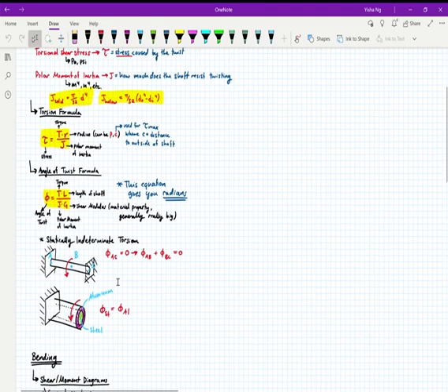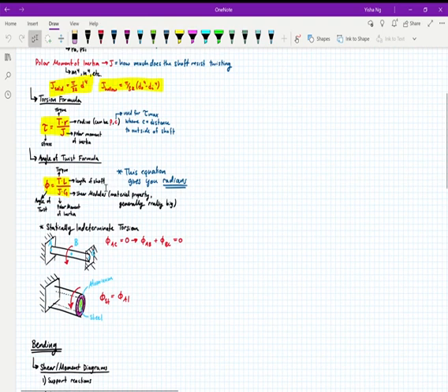You've got your angle of twist formula. Phi is TL over JG. We talked about everything except for G, which is the shear modulus. This is a material property. It's generally a pretty big value, so don't worry if it's really big. And this equation gives you angle of twist in radians. So if you're looking for degrees, make sure you convert to degrees.